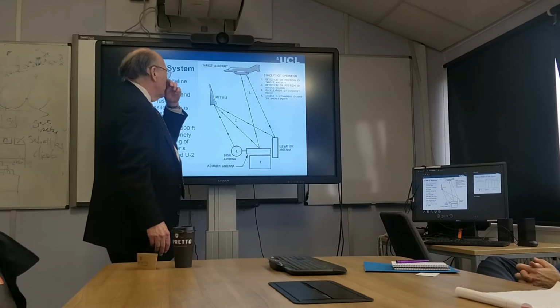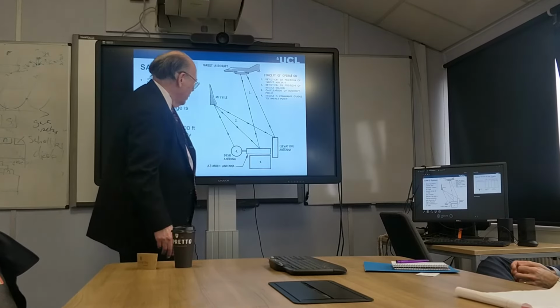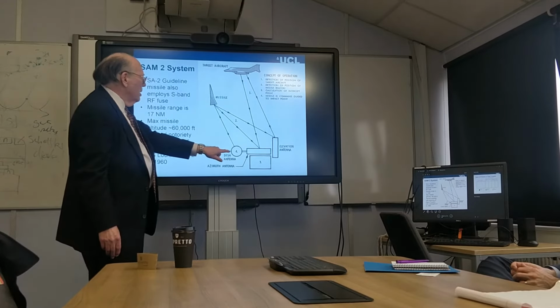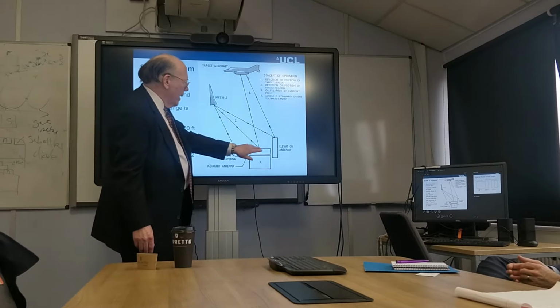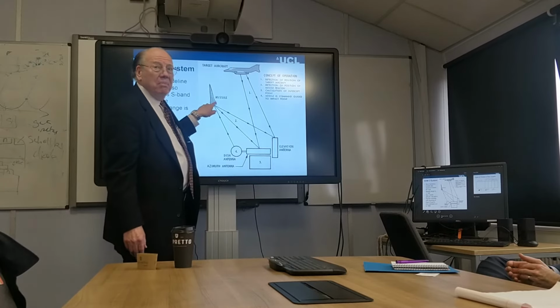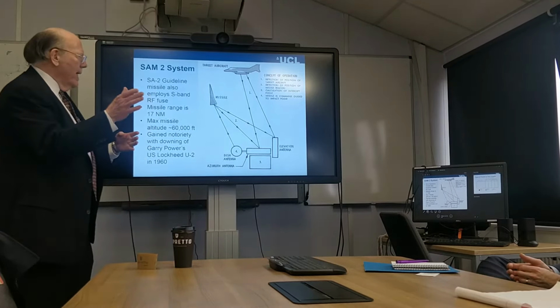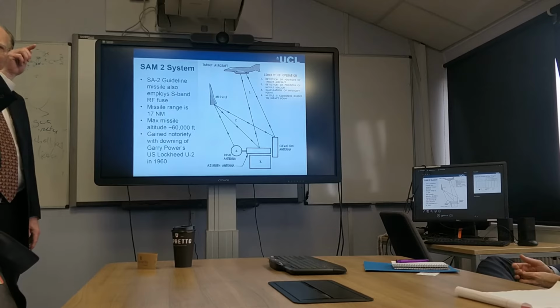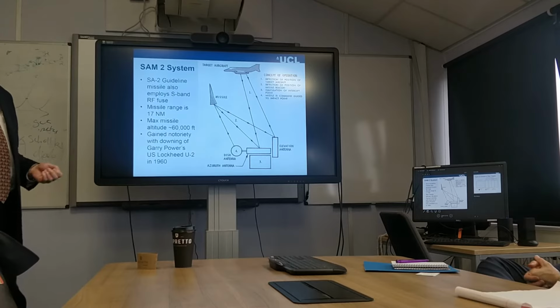And then, as I mentioned before, there are the two radar systems: elevation scan and azimuth scan. And then it's got this dish antenna that transmits an L-band signal. It transmits a guidance signal to the missile. And then the tracking system, besides tracking the aircraft, tracks the missile as well. It's called a trackball scan system. It's got two beams, and ideally, when it locks on a target, it gets the target right in the middle of those two beams. And the system is pretty robust against countermeasures.